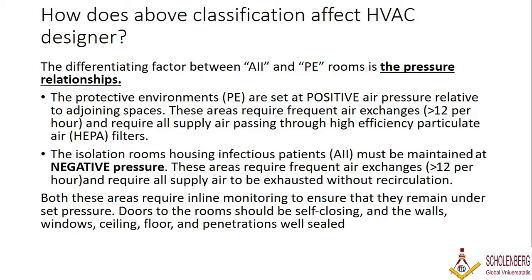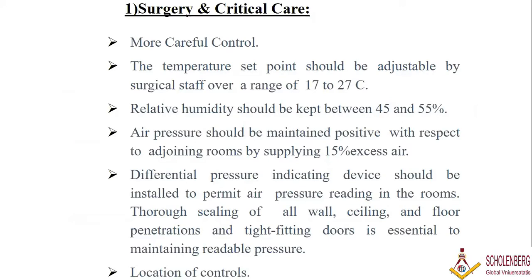Both these areas require inline monitoring to ensure that they remain under a certain amount of pressure. The room should be self-closing, and the walls, windows, ceiling, floor, and penetrations should all be well sealed. But this may not be the HVAC engineer's work. It's the architect's, but it is our duty to inform the architect when they are doing all these things.